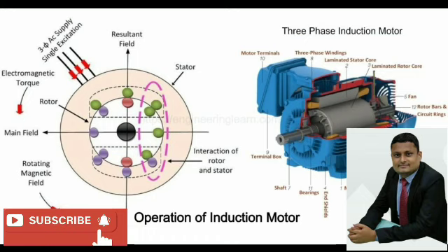After each 10 centimeter length, we need one duct. Since L equals 13.83 cm, there will be one duct in the stator. The thickness of that duct will be 10 mm. Net iron length equals 0.9 into 0.1383 minus 0.01 equals 0.115 meter. In this way you can calculate and get the result.